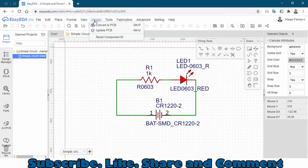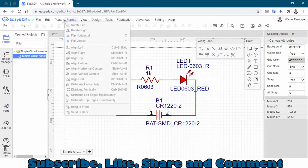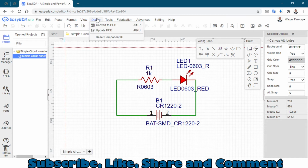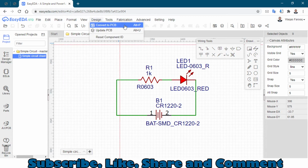Now go to designs, and there are some other options. We will go through it, like place wire, bus, everything is here. So you can select the wire by just pressing the W button. But now I will go to design and click on convert to PCB. Now click on this convert to PCB, or you can just press Ctrl Alt P. So I will click on this.